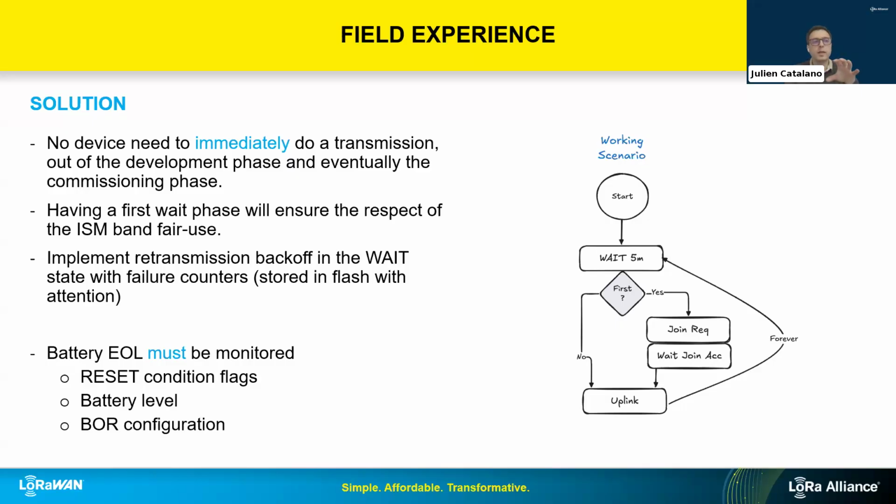And we are really on the topic of today, because today we are talking about this technical recommendation TR007. And actually, if you read that recommendation, in there we advise, even for devices which have a LoRaWAN stack under 1.0.4, which, you're right, Paul, is now using incrementing numbers as nonces.